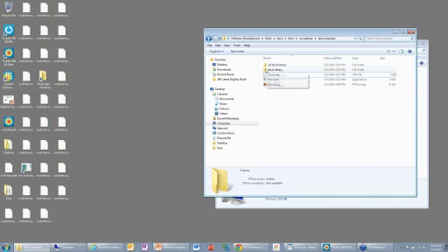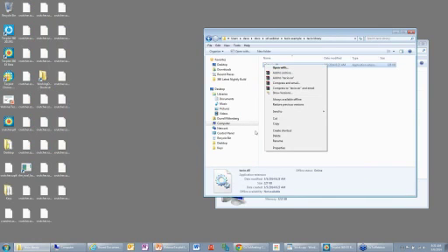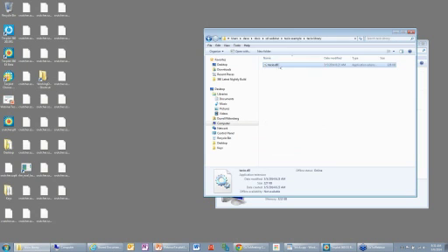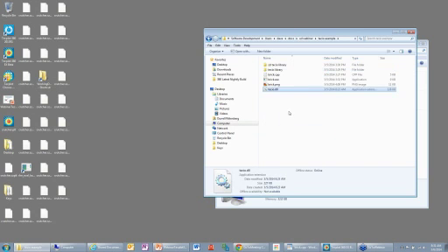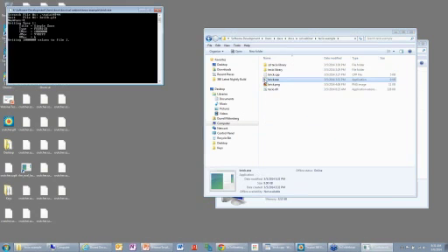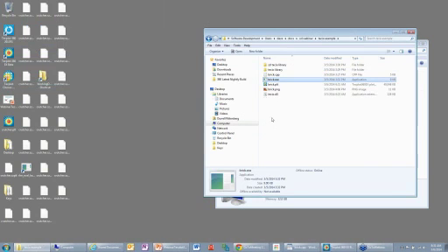So let me first off run this with what I guess I could call the legacy TecIO library. I do that just by copying it into the same folder as my executable. Now on Windows, Windows will preferentially load any local DLLs before it loads any others. So I'll just launch this by double-clicking on it. It's a batch code, so all we're going to see is a DOS window while it runs, and we get some diagnostic output, which I haven't added to the new library yet. But it's created brick.plt, which, as you can see, is about a 40 megabyte file.